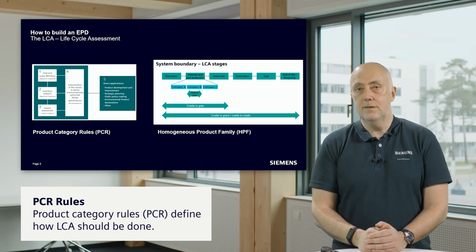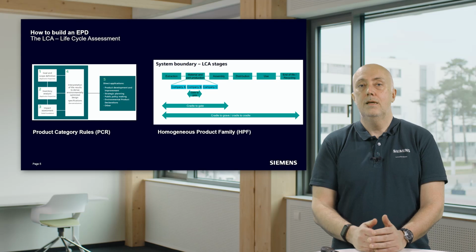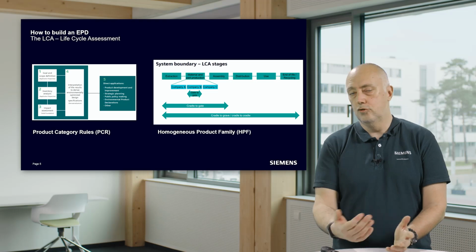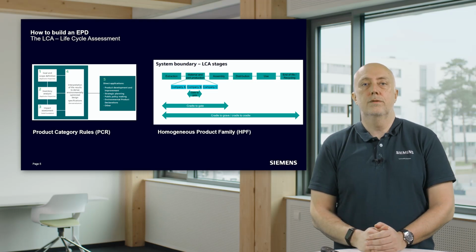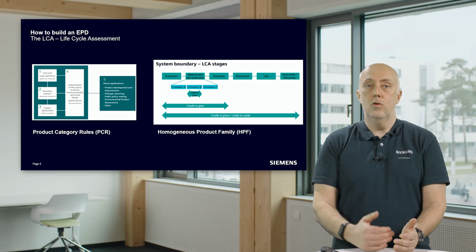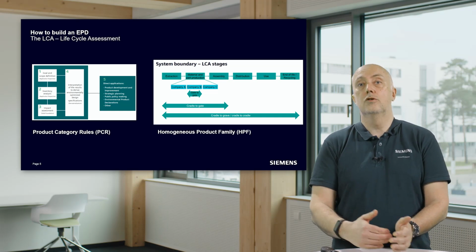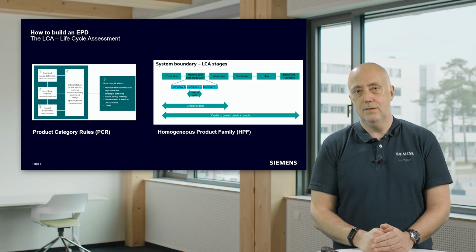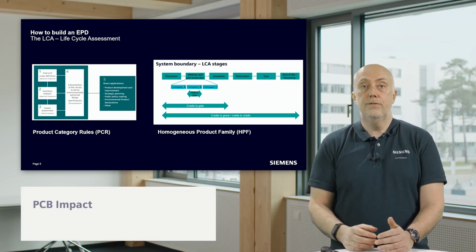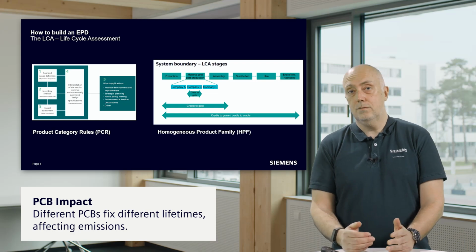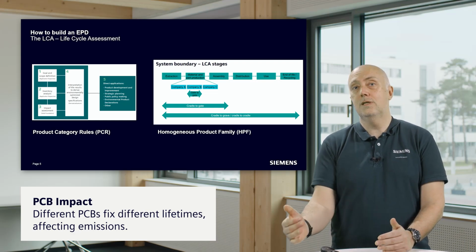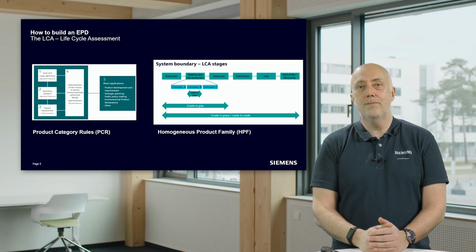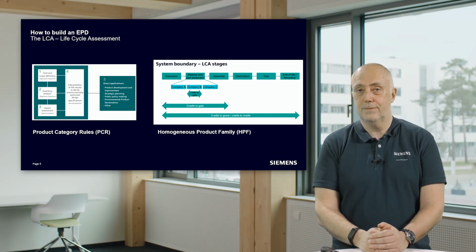One example of non-standardization having an impact on the results is the lifetime of the equipment. Our products will have, for instance, resistive losses, joule losses, during the lifetime of the equipment. So we are making assumptions on the load under which the equipment operates, on the source of energy, and on the number of years the equipment will operate to calculate the emissions. Some PCRs will fix a lifetime of 20 years, while others, for instance the ones that we use in Siemens, will use 40 years, doubling the emissions in the second case. So PCRs have really a strong impact on the final emissions documented for the product.